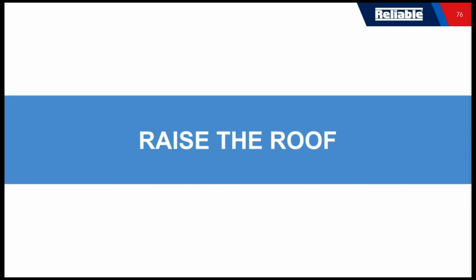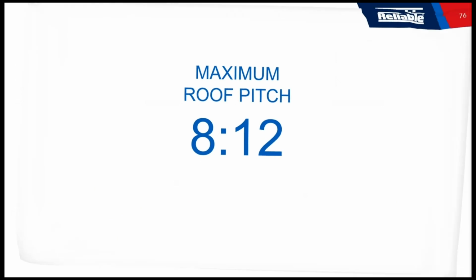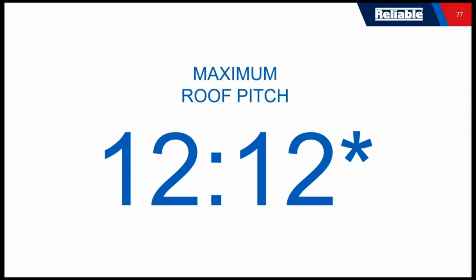And one thing, the sprinkler's been out for a while, and you always got to keep up with the data sheets. Everything changes every so often with manufacturers and their products. What we did just this past fall was raise the roof. Our maximum roof pitch for use with our products has been 8 and 12 since they came out. Well, we found a way to enhance some listings and get our listings up to 12 and 12 roof pitch.